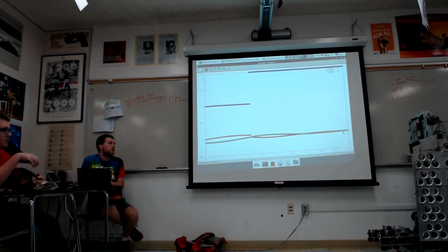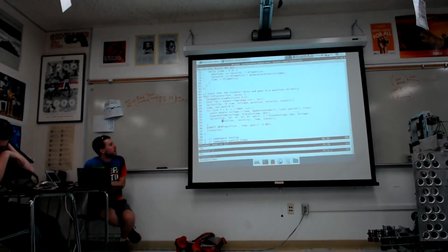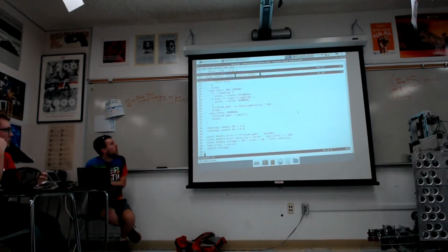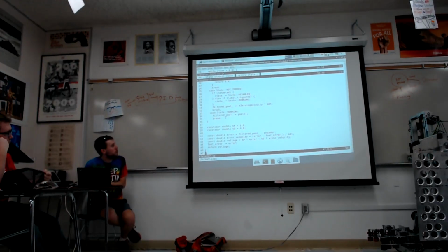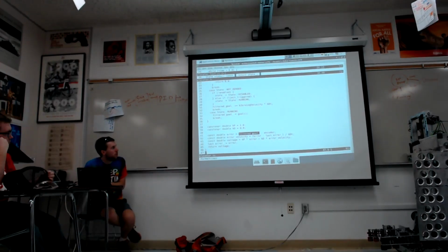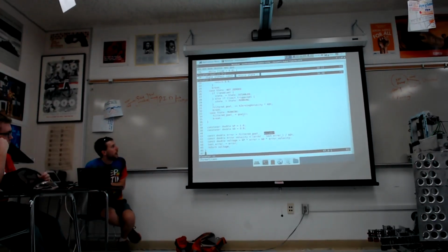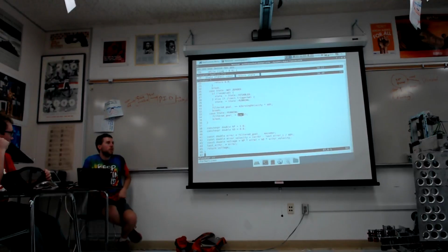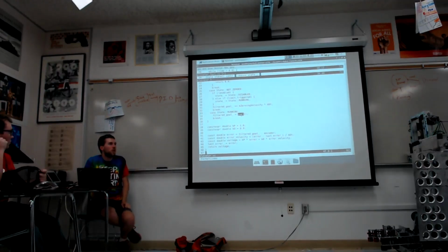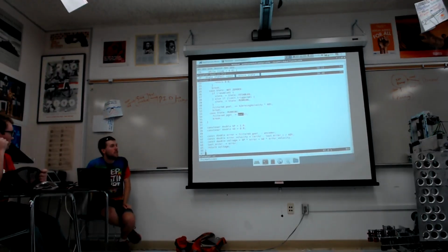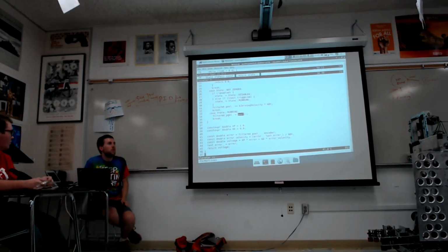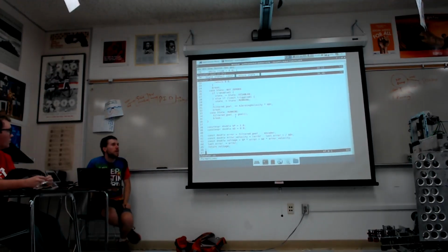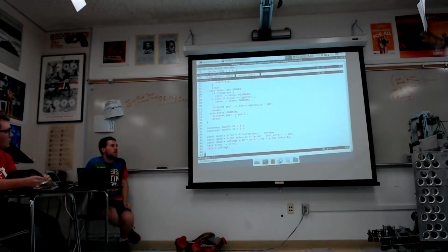So what you were pointing out: when we go into running, our control loop goes to filter goal minus encoder, and this just passes through whatever our user asked. So if 0 on our encoder is not 0, the actual robot 0 will go to the wrong place. So we need to start adjusting this stuff here. Does that make sense?